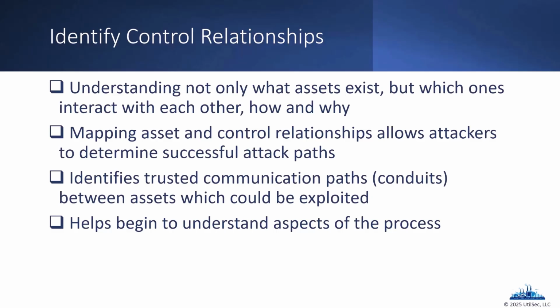Well, we can look for things like communication between those hosts. So if we're able to watch for network traffic, or we have PCAPs for the environment that maybe a client can provide for us, we can use that to, again, start understanding the environment, those assets, how they communicate, what they're actually saying. Remember, the nice thing in OT environments is that most network traffic isn't encrypted. So we can see the information being sent between those different hosts. So if you have an HMI that's sending commands to a PLC, you're going to see what those commands actually are.